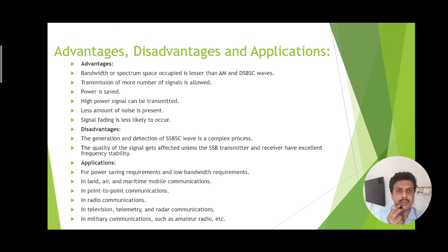Less amount of noise is present. Yes, it is obvious. When the range of frequency in the modulated signal has been reduced, the amount of contamination of the signal by the noise has also been reduced. The signal fading is less likely to occur.